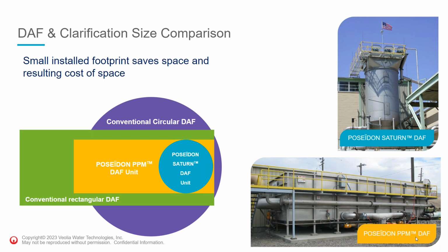Our Poseidon product lines, as I mentioned, it's very important to have a small footprint in these recycled paperboard plants. Many times we're coming into the plant as a retrofit to replace an old clarifier that has seen better days. It might be 30 years old. It might not be in such great mechanical shape, or it's been undersized as production increases have happened over the years. So we sometimes have to come into an existing plant and try to shoehorn in a new piece of equipment while the old clarifier continues to run.